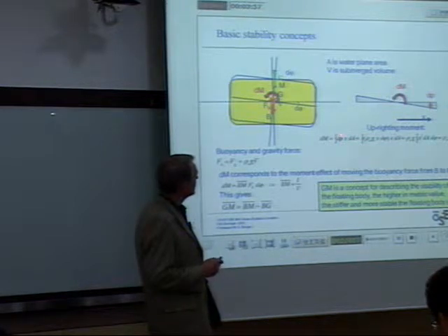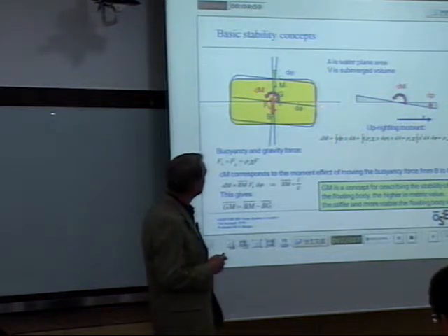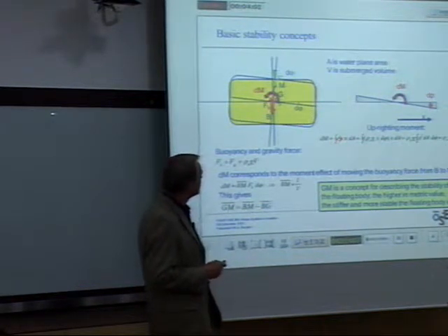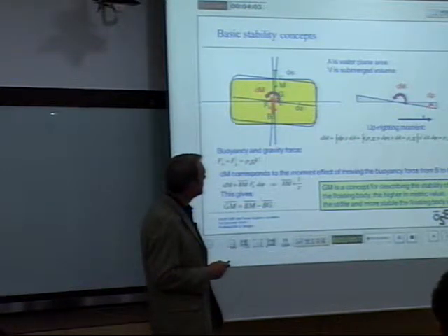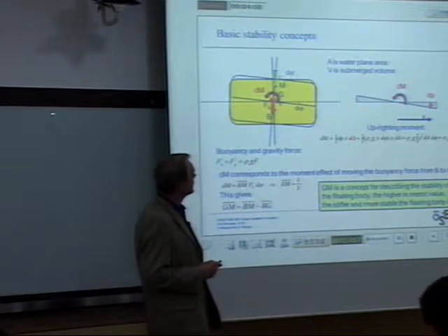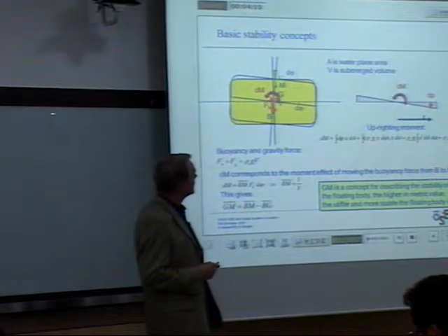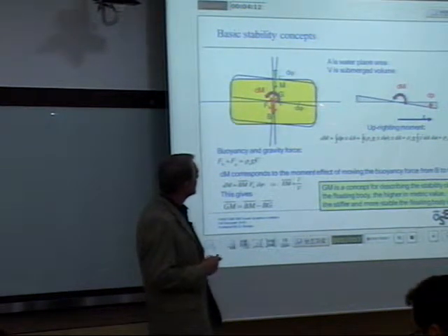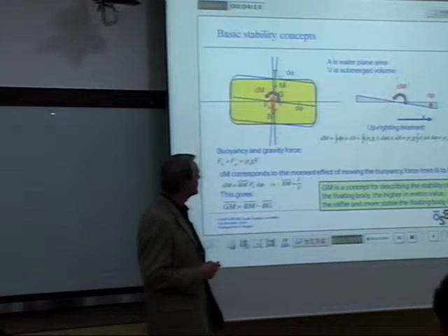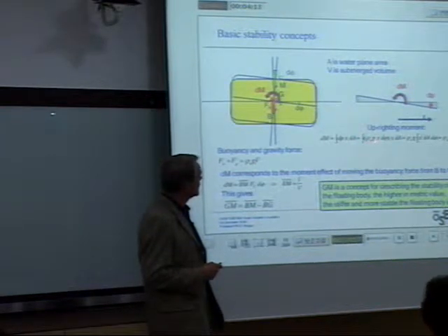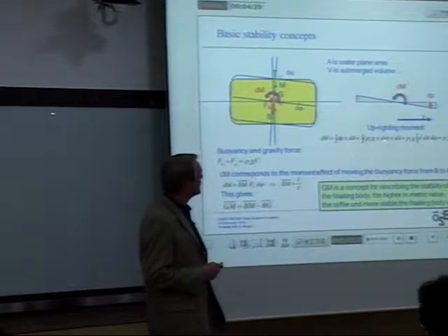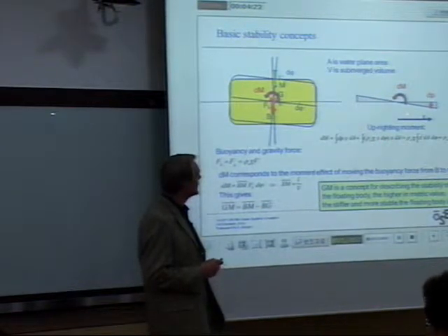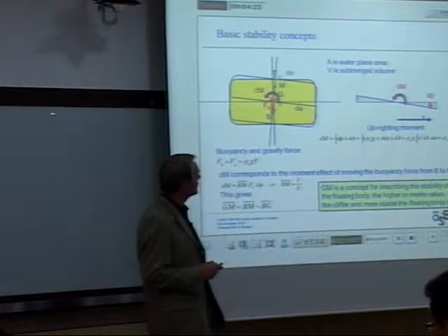And that is the integration over the water line area of the increase of pressure, and of course the moment arm and the area dA. So integrate that over the water plane area, right? And the pressure is rho g times x d phi. That's how far it goes into the water, x times d phi, right?